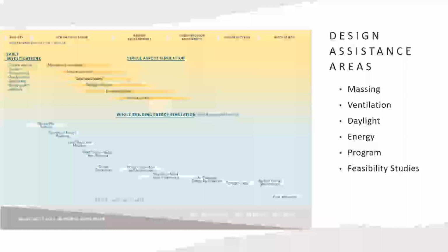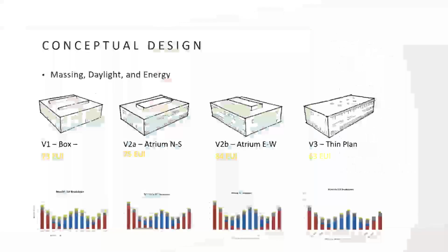Because remember, while we care about energy efficiency, occupant comfort is also important. Because if occupants override or are not comfortable with the current control strategy you have implemented for your building, they will override them, and more often than not, you'll be using more energy than you actually intended. I've seen that in way too many buildings.